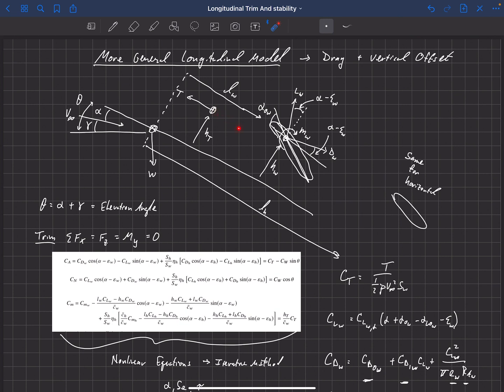And so this now creates a large nose up pitching moment, and we're creating a large nose up pitching moment from our elevator back here. And so if the pilot doesn't correct quickly, the aircraft will just stall because it will quickly pitch the nose up and can stall the main wing of the aircraft. And so this can be a really dangerous scenario.